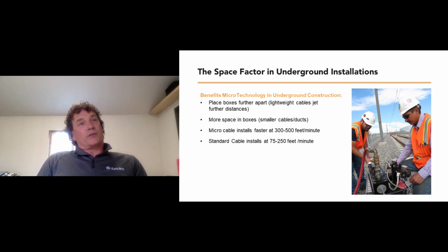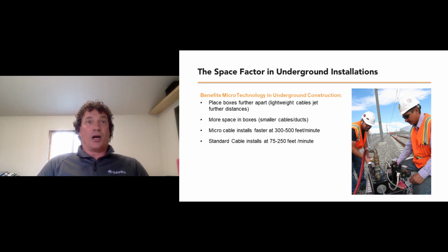One story was we were on a job site where we had a 2.5 kilometer jet, and it was an introduction to microtechnology for both an end user customer, a small telco, and a new contractor. So we did a demo day out on a job site, and we set up the equipment and a small reel of fiber. It was only 2.5 kilometers. We set it up and did the jetting in a very short period of time. The one comment that always stuck in my head was from the contractor, who said what you two guys did in a couple of hours would have taken his team of 7 men the better half of a week. So we're saving a massive amount of time.